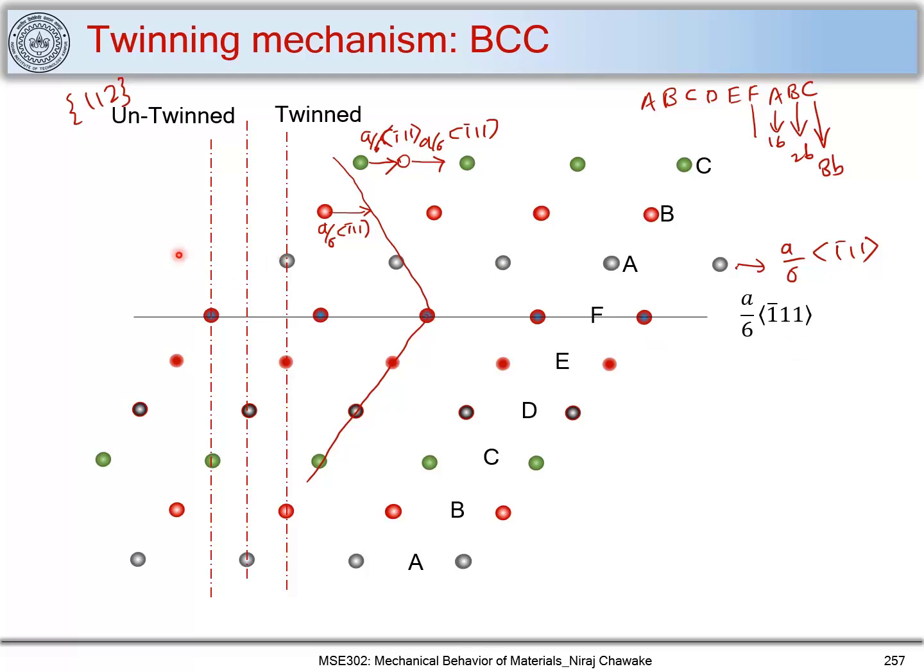So when we moved these atoms, or this layer of atoms, we have seen that this configuration was not energetically favorable. So we call that an untwinning process. Rather, this position, so let me mark it over here. We have initially this A layer over here, and when we moved in this direction, this is an untwinning process. While if we move in this direction, this is a twinning process. So you have untwinning happening over here, and you have twinning occurring here.